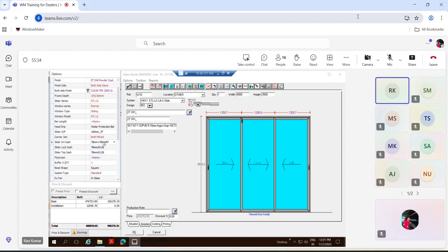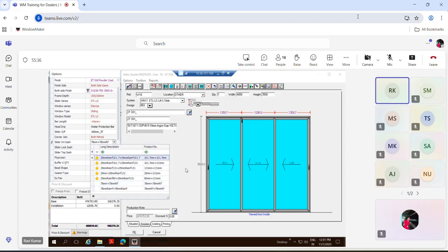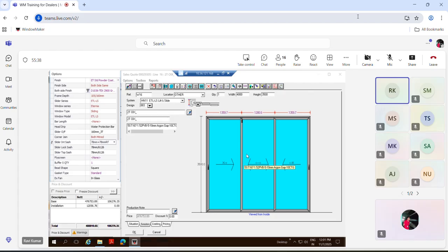So in this series, only single point handle will come. Means one side will come with reinforced profile, other side will come with handle. So due to that, the earlier error was showing. Once you change the interlock, the error will be removed from here.